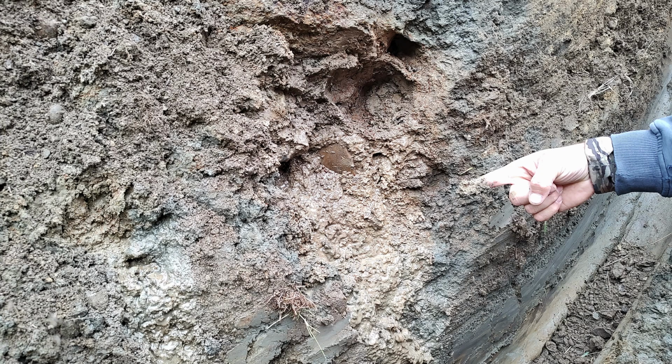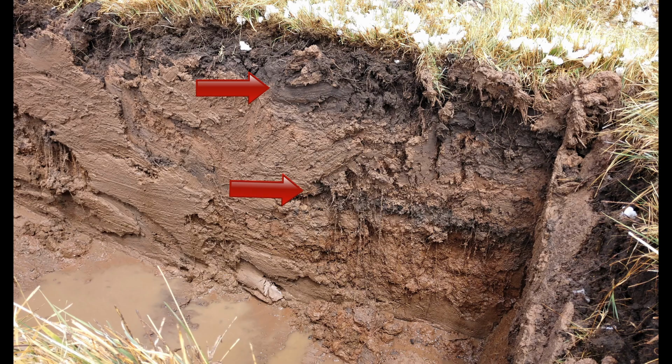The person's hand is pointing to an underground stream that's flowing in a collapsed drainage structure that was made from clay tiles. This structure was exposed by digging the core trench for a groundwater dam. The groundwater dam we're building here will block water flowing in the black-colored topsoil near the surface and in a buried layer of topsoil that's beneath the surface.